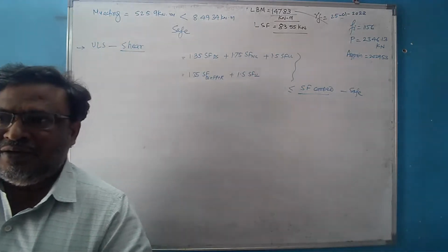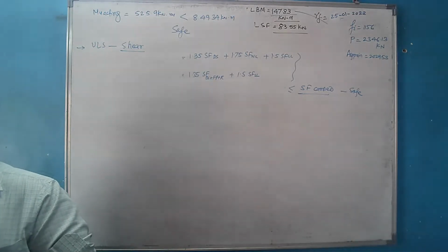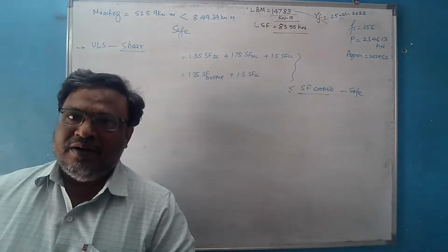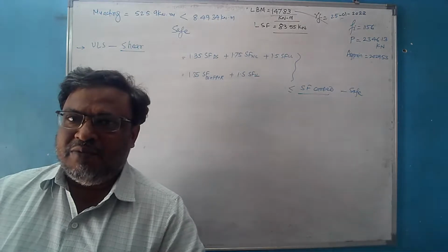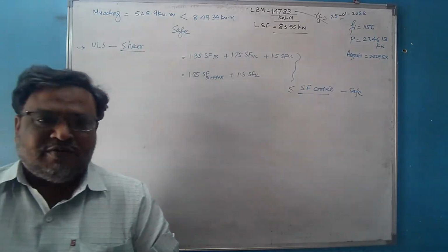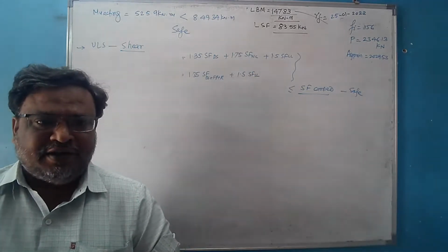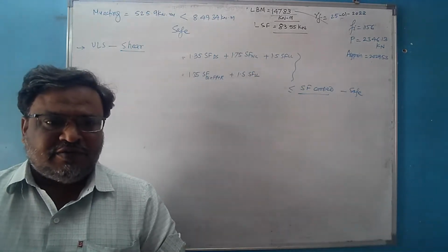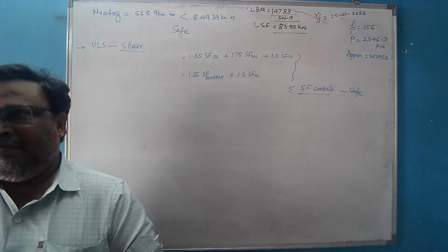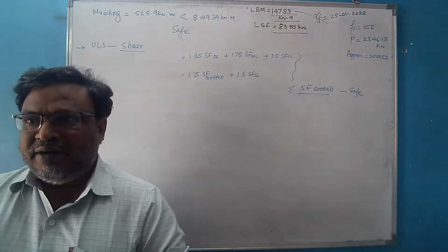We had determined the forces acting on the bridge, the dead load because of the deck slab. First, we had assumed the thickness of the deck slab approximately on the basis of a thumb rule, say 50 per meter span. On the basis of that, we had determined the self weight when a 1 meter wide strip was considered from the carriageway width. Then the self weight of the bearing course was also considered. The bearing course was considered as 100, and we had determined its self weight also.